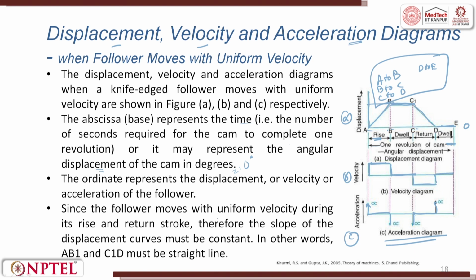Since the follower moves with a uniform velocity during its rise and during its return, the slope of the displacement curve must be constant. In other words, AB1 and C1D must be straight lines.